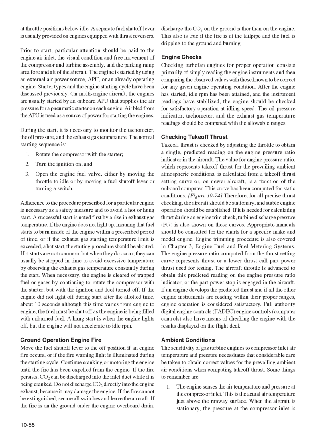A hung start is when the engine lights off, but the engine will not accelerate to idle RPM. Ground operation engine fire. Move the fuel shutoff lever to the off position if an engine fire occurs, or if the fire warning light is illuminated during the starting cycle. Continue cranking or motoring the engine until the fire has been expelled from the engine.